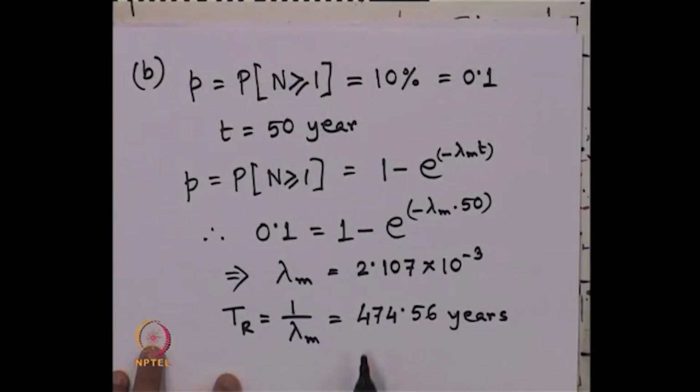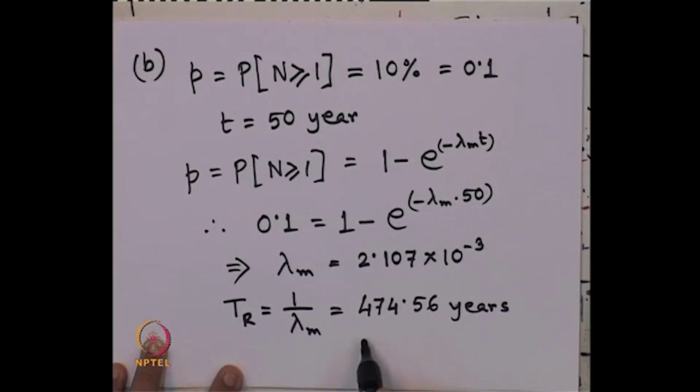In the theory we also learnt that it is about 475 years of return period, and we got the same thing here. So, that 475-year return period earthquake is classified as the contingency level earthquake, that is, CLE.